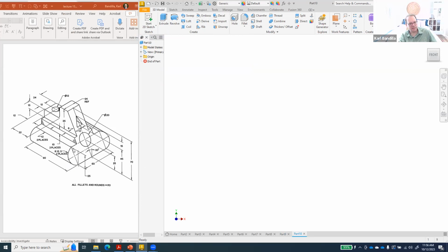It is drawn as if this radius of 12.5 is in this sloped plane, right? Because it's connecting here, it's connecting there, so it looks very much as if it's in that plane. But it also says that the overall height has to be 25, which is not possible, because 12.5 times 2 is 25. This would have to be higher if this was actually in the plane.